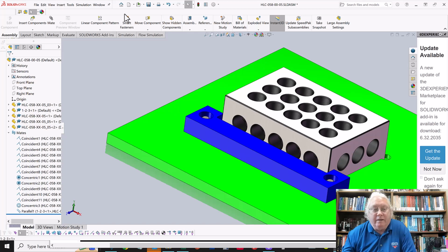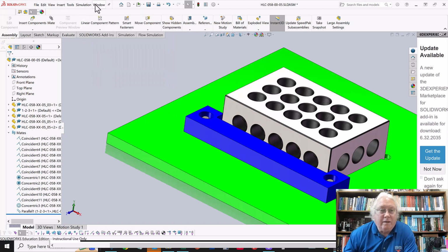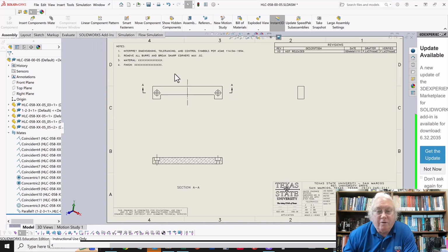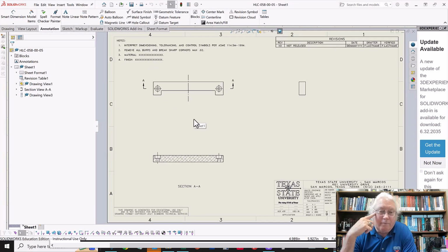So now that you've got that understanding, you can go up to your drawing. Make sure you choose the right drawing. You're going to define those datums. We've got different datums here than we had on that first video. You'll define those datums just like I defined them in that assembly model. And then you'll add those dimensions to the holes located from those datums. And then we'll put feature control frames. So the next video we'll talk about how to add those feature control frames.